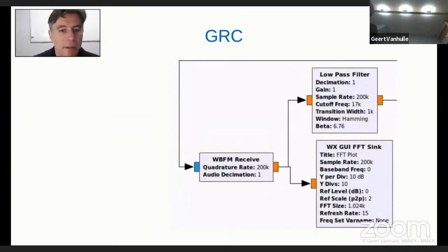Now the next stage is, I have this 200 kilohertz bandwidth. Of course, this is a modulated FM signal. I will have to demodulate it. Now I will go from a modulated signal to a demodulated sample stream. The thing is, I can't really feed complex samples to an audio card. And a complex audio signal doesn't really make sense. We can only listen to a normal sample range coming out of an AD converter from a sound card.